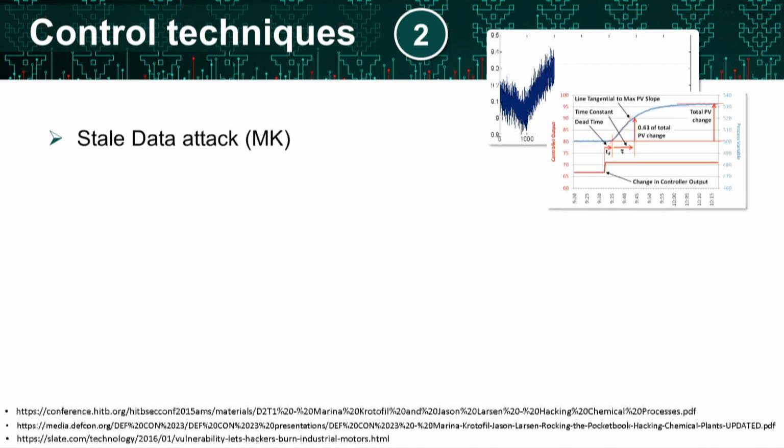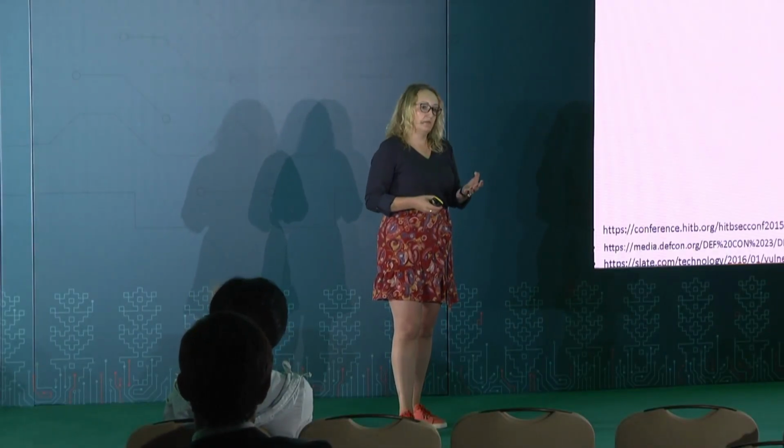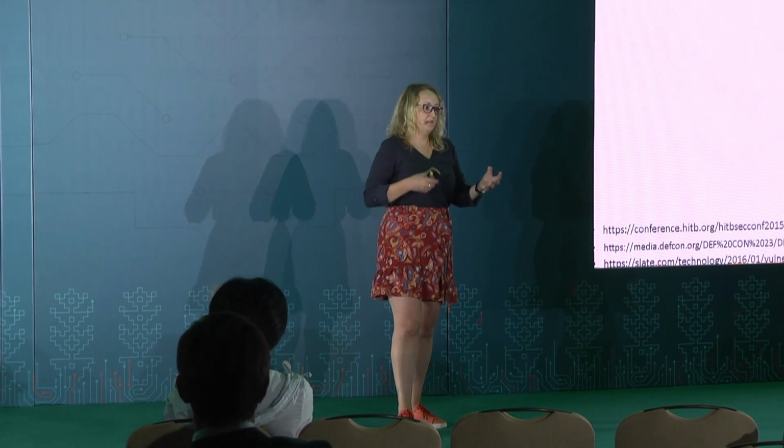And if we combine together the knowledge about the time constants of the control loop configuration and the state of the process, and we strategically lock in the memory a specific stale data, then we will be able to manipulate the process at will, bring it to the state which we want.